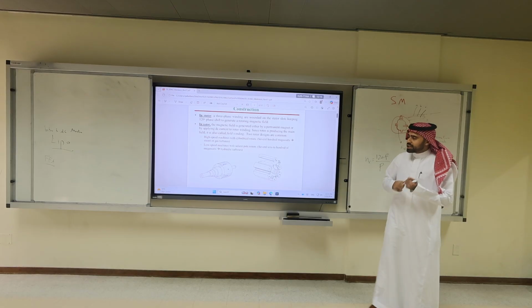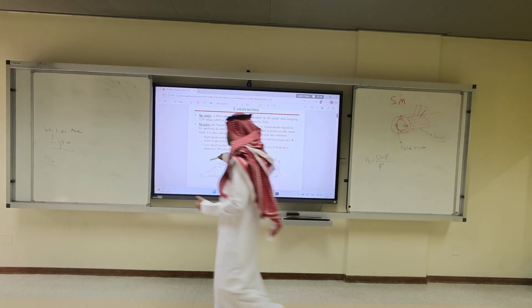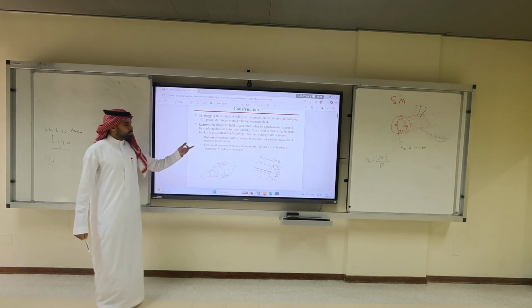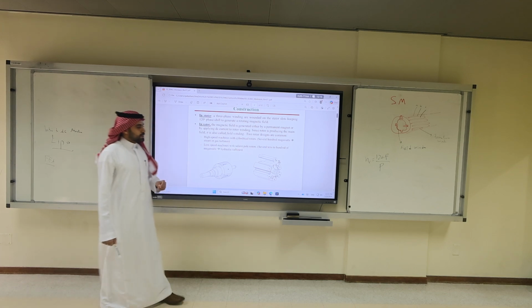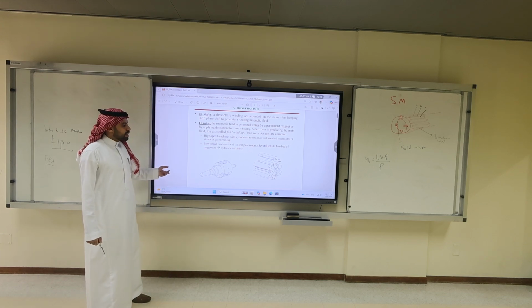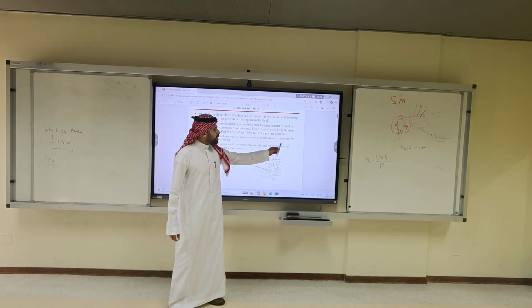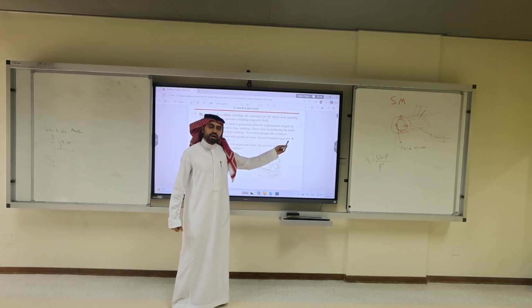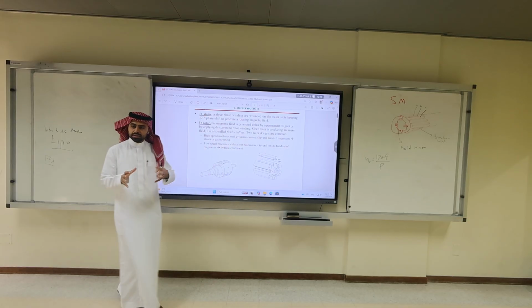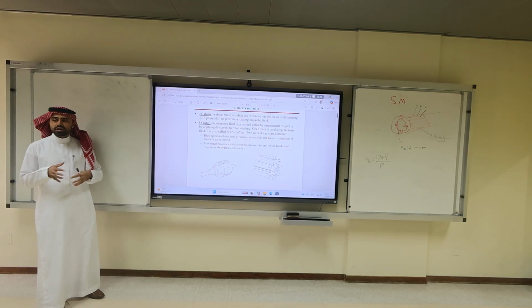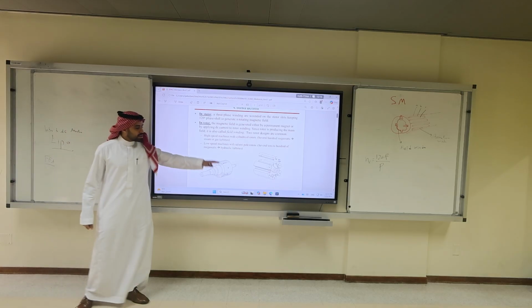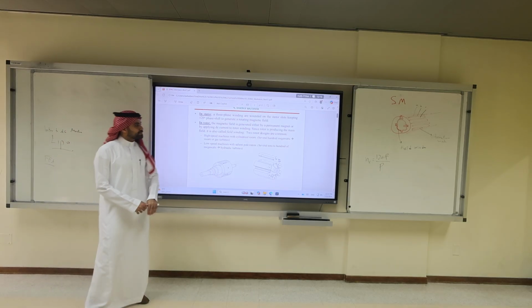For the sake of excitation, it doesn't matter whether it's cylindrical or salient poles. Now, as you can see, this is tens of hundreds of megawatts. This is just a few hundreds of megawatts. So usually small generators or small synchronous motors tend to have the non-salient option, the cylindrical.